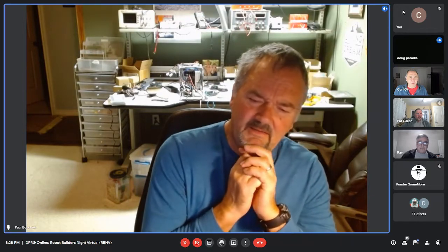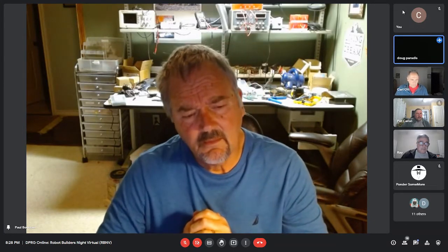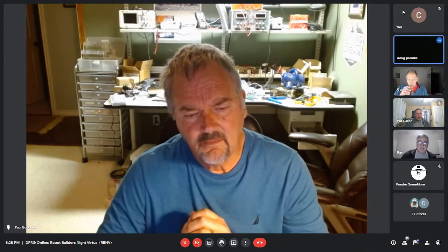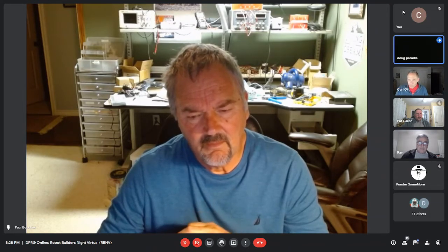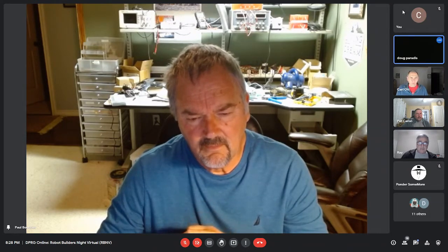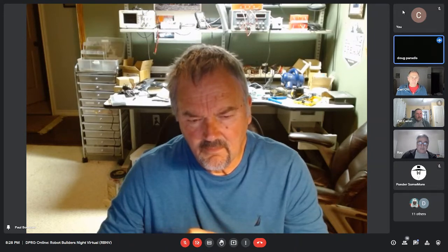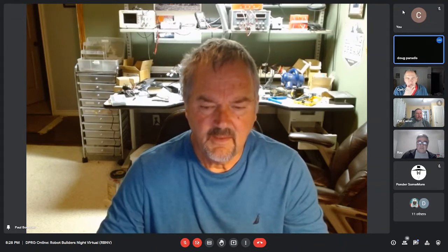Okay, thanks. And then the other, Paul, there's one last thing before you leave it: the BNO055 has a serial port mode too. Just so you know. But yeah, that, Doug, has the same issue though, because if it's a voltage signal instead of a current, it's a high impedance voltage signal, so it's going to be susceptible to capacitive loads and EMC, noise coupling in.